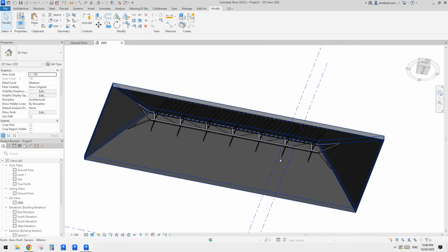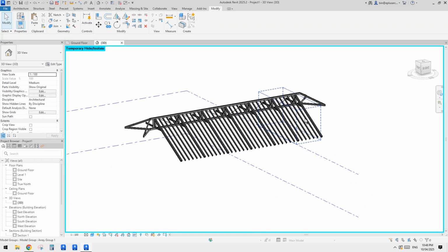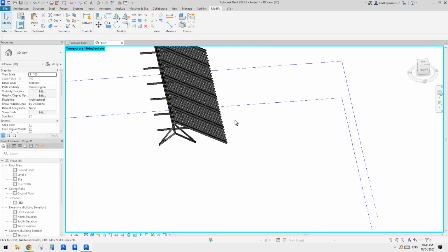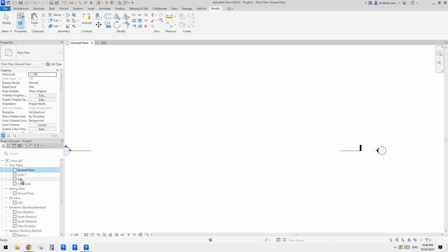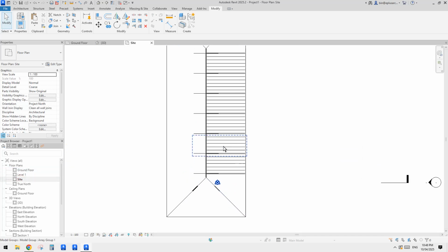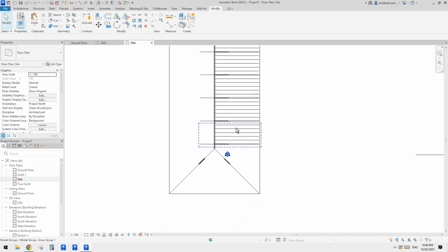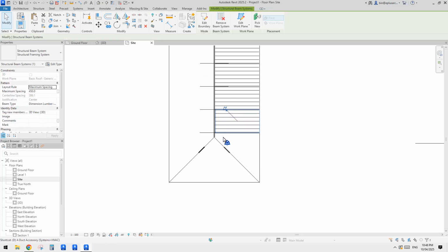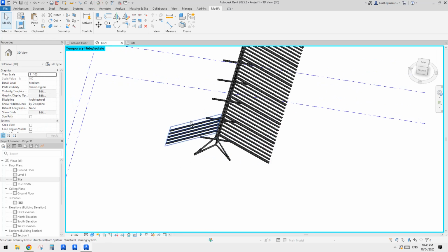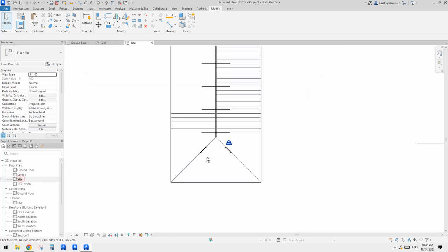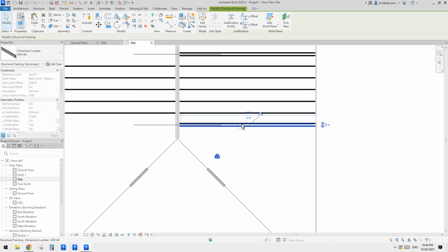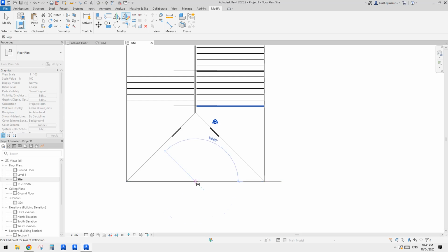It's a little bit dark. Maybe I'll just hide the roof. Yeah, that's better. So, okay, maybe we need it on the other side, right? So let's go to maybe side plan. So wireframe. So I'll see if I can just mirror the beam system to the other side. Yeah, good. So go to 3D view again. So we have this, and maybe we need these two as well. So let's go to the side and tab select, and mirror to the other side.